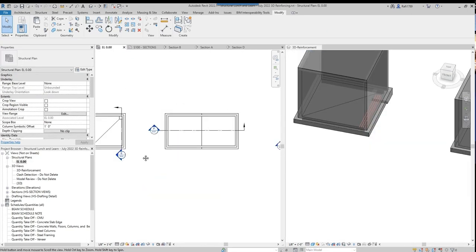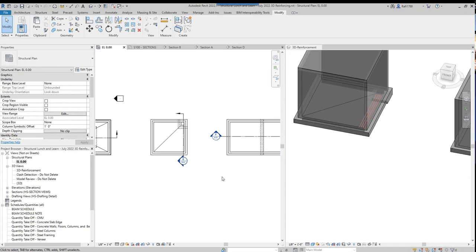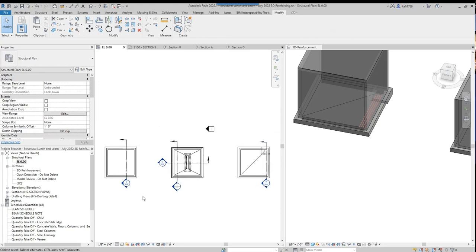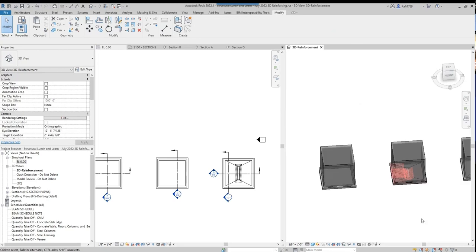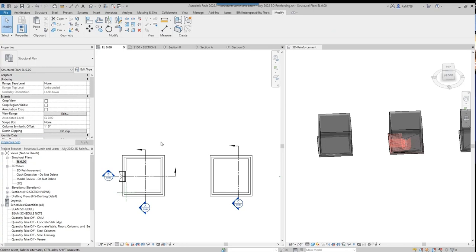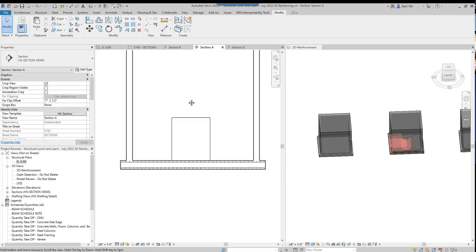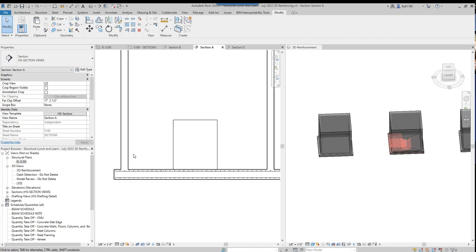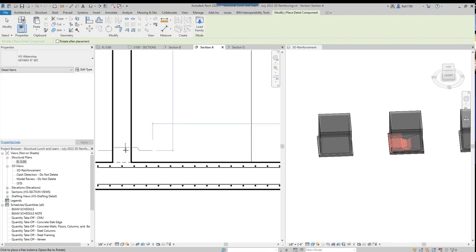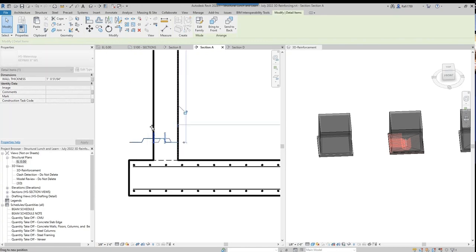Moving on to walls. So the walls, oftentimes I'm doing them from a section perspective while I'm looking at the 3D. So let's go back to this first one and let's go to this section A. So I'm gonna put in some detail components, let's just say with a keyway and water stop, just so that we can look at a typical scenario.